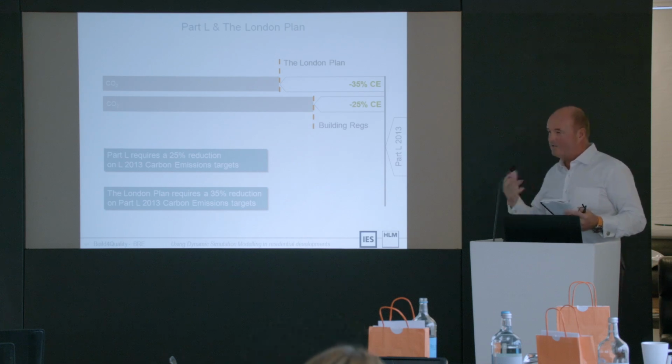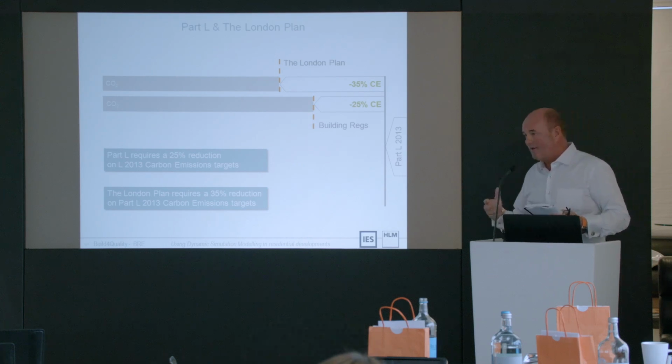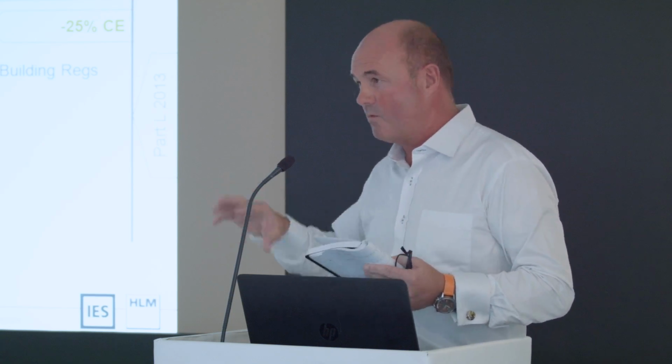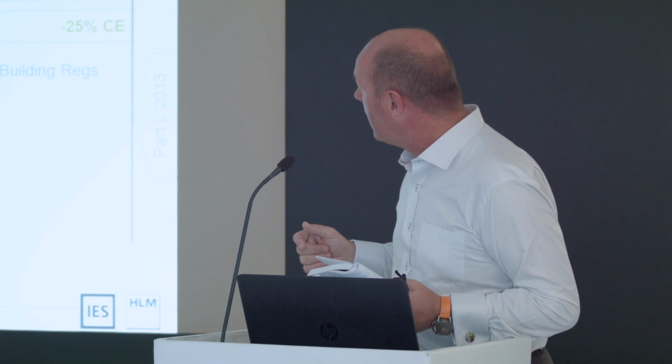We tend to think we need to move on from that because the building typology in residential is becoming more sophisticated. SAP is a slightly more historical tool that is probably more compatible, in our view, with more volume house types. When we look at high density, highly complex residential schemes, we think we need another avenue of analysis.